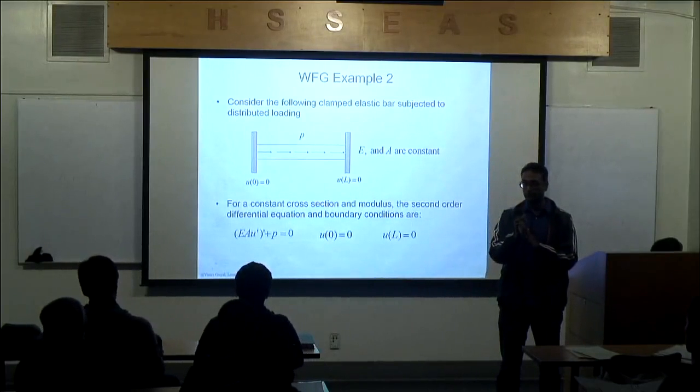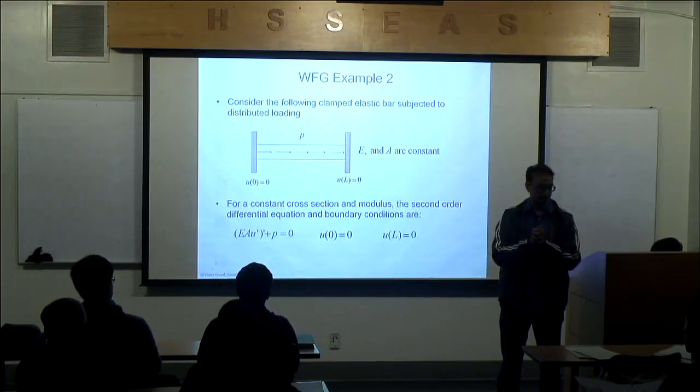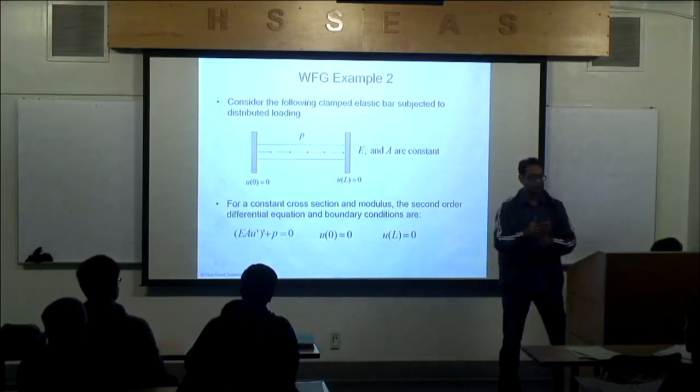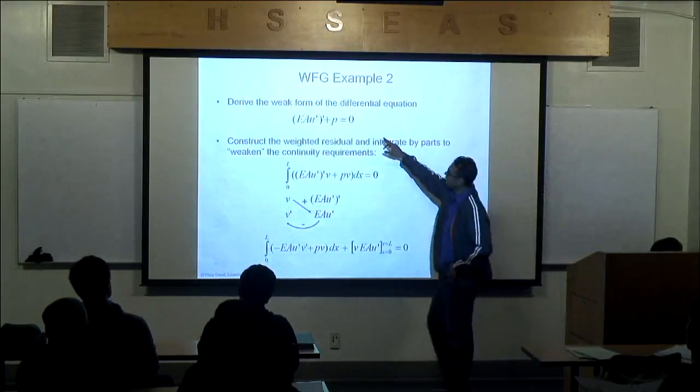I'll first form the residual function, multiply by the weight function, and integrate it over the domain, 0 to L, in this case. And then I will weaken the continuity requirements. Those will be the steps. And so here in this example, I have the differential equation.